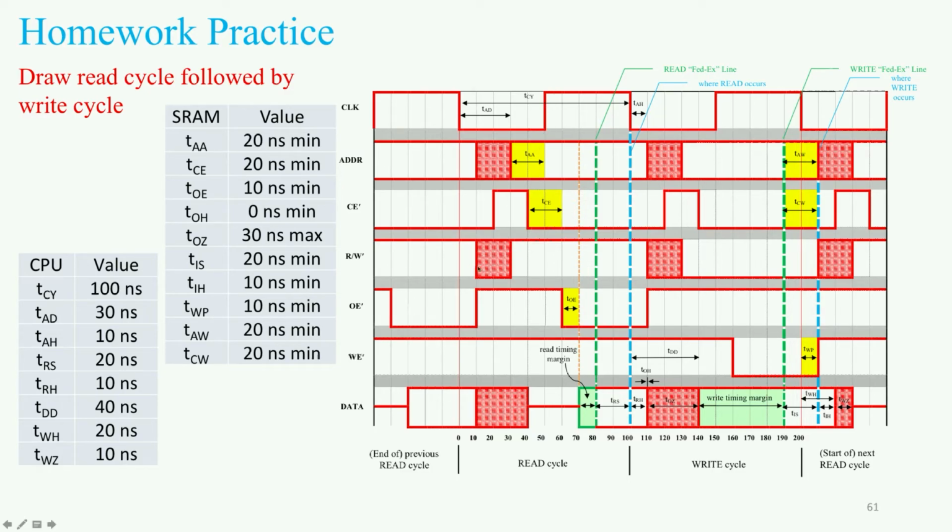Read write, it is transitioned based on the clock signal. Oh, I'm sorry, no, the read write bit is not transitioned based on the clock signal. It's just controlled by the CPU. So it doesn't matter that the clock signal goes high. But these signals related to the SRAM are controlled by the clock. Okay, so the clock going high effectively begins the transition of this output enable bit.